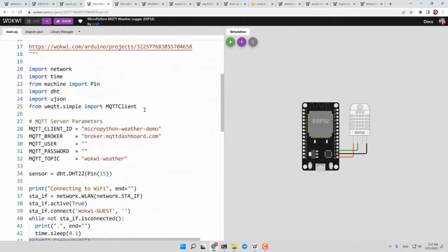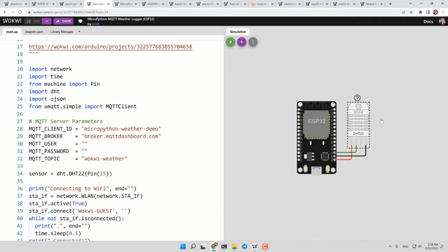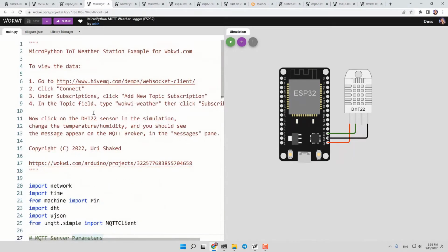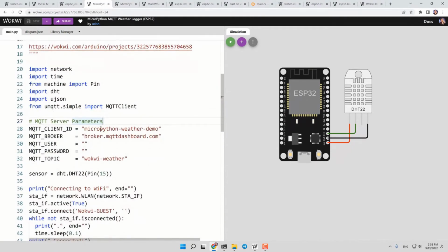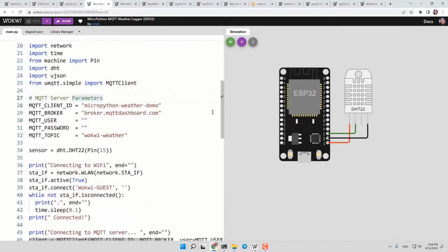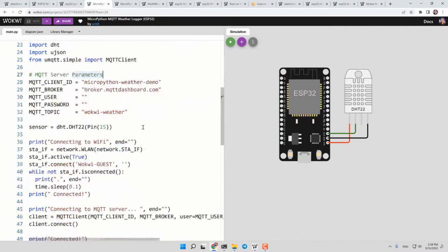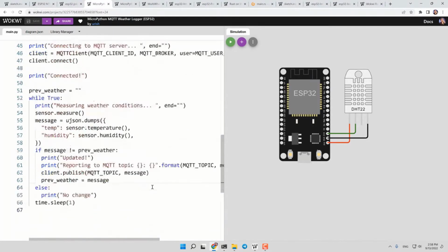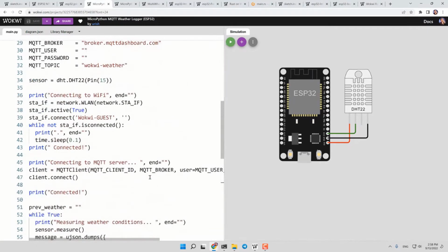It's simple and it includes a complete IoT project, as I would call it. It's again the ESP32 with the same sensor we have seen before, the DHT22 temperature sensor. And you can see the code now is written in Python. When we start a simulation, the ESP32 will actually load the MicroPython firmware, and then use this firmware to run this code from the virtual flash on the ESP32.